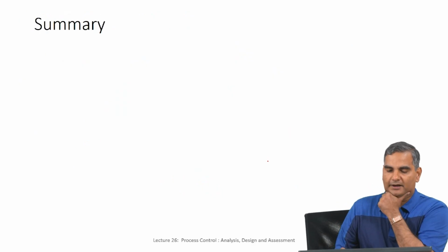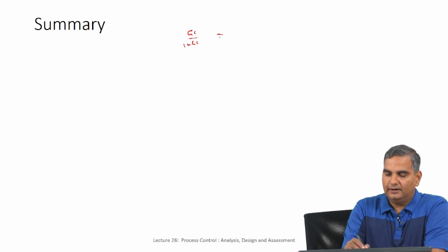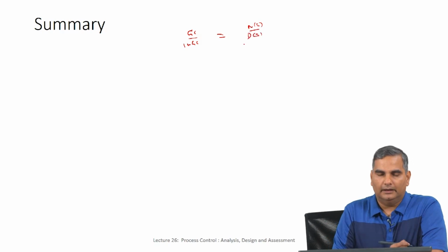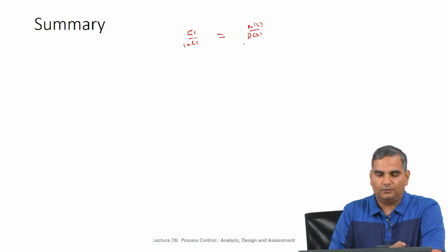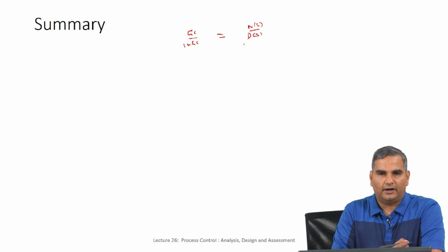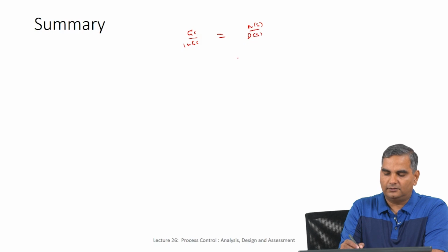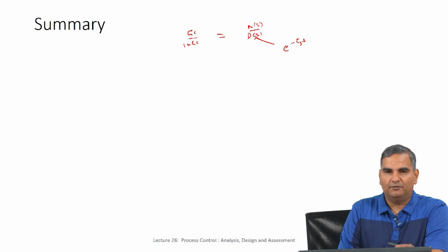Okay. So, in summary, we said whenever I have GC by 1 plus GC, typically we have been saying this is some numerator by denominator, and then you can look at the stability of the systems by looking at the poles of D of S, and if I can get it in root resolved form, then I can use partial fractions. Then we talked about root stability table when I do not write it in root resolved form, and then when we came to time delay systems we got into this issue of this term having e power minus tau ds in its functional form. Then we said we have to look at some way of handling this.